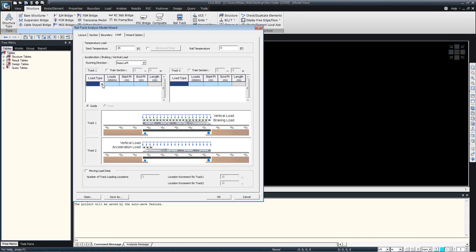Here we can consider the braking load. So braking load, as per the discussion in the PPT, I can give it as 4.9. Span start point, I can give it as 300 meters or something like that. Okay, so I can give it as 300 to 500 meters, so from the embankment I'm starting. Similarly, the vertical loading that is coming for the train will be 27.2, and this I can give as 300, 500 again. So automatically the length will be considered.